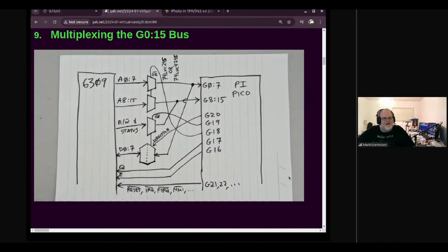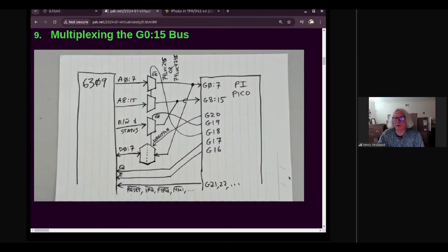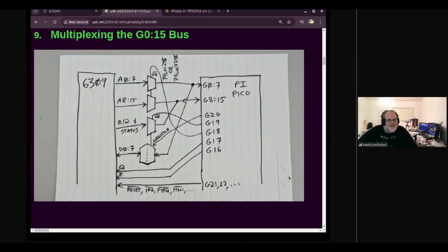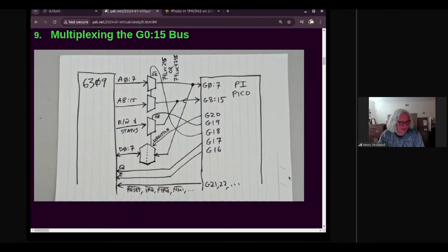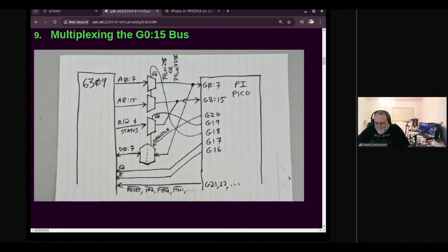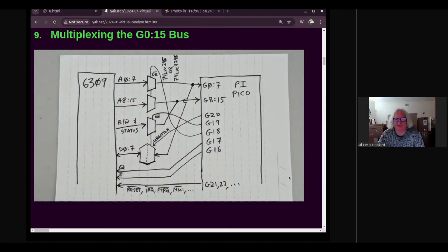Henry, I have another question from the audience, and I have a question myself. Okay, go. Daddy Burrito says, are aftermarket 6309 chips expected to be compatible, like something that can be bought from Jameco or somebody like that? Aren't those usually just old new stock? I think it's all old stock, and I get them from eBay. I just type 63C09E on eBay and find the people that are selling them in large quantities for cheap instead of individuals for expensive.